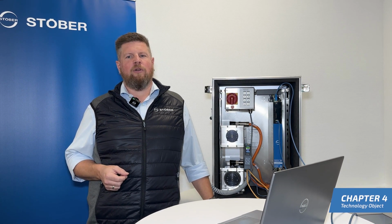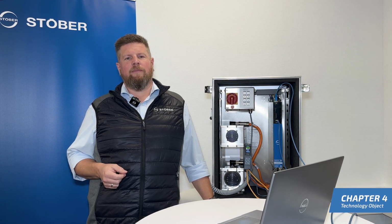What did I just show you? I created a new project in the TIA portal. After that, I installed the GSD file from STOBER and added the S7 1500 controller and the SC6 drive controller to the network view. I interconnected the ports, configured the Telegram with PROFIdrive modules, and activated isochronous mode.